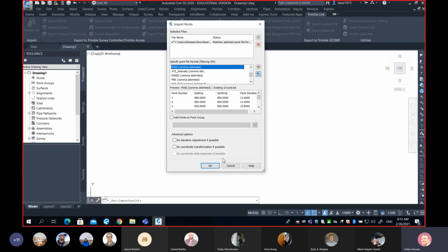Never do that. Because if you hit OK right now, can I ask you where these points will go? They won't have a group at all. Yeah, they go to _All Points, and if I do the same thing and bring in the other points, again we have the same problem. We have a mix within the same point group. Please don't do that. Remember, when I say something, for some of you it looks trivial, but I can tell you over the years, those are very common errors that students fall into.